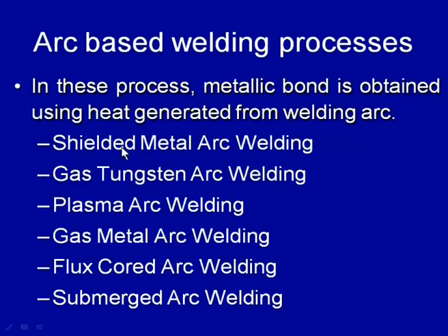the base material, and the heat generated by the arc is used for melting both the consumable stick electrode and the base material, and development of the molten weld pool, and subsequently solidification results in the weld joint.